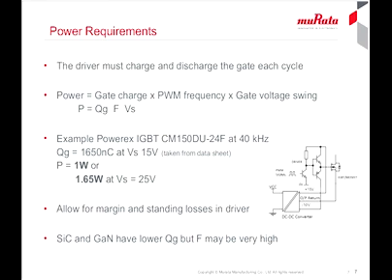The gate charge value is found from the device datasheet, listed as QG or total gate charge at a particular gate voltage. It is not a very exact figure, so some margin should be allowed. Also, the datasheet will often state the gate charge at a different voltage swing to what you want. You can simply proportion the charge to the voltage swing you want.